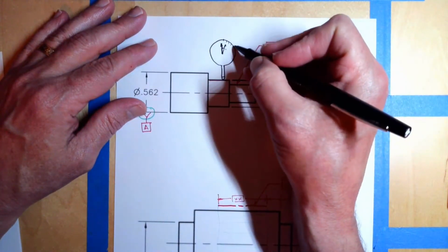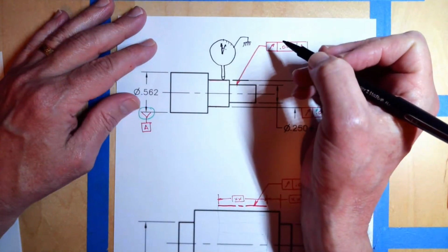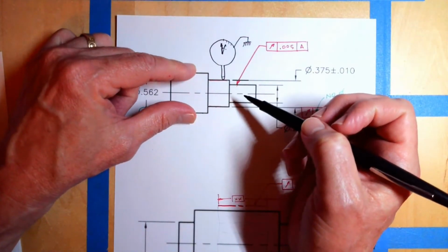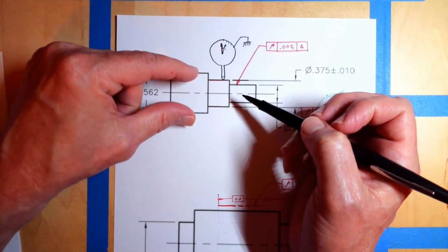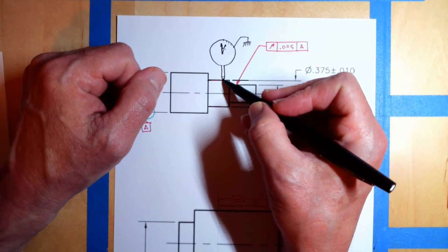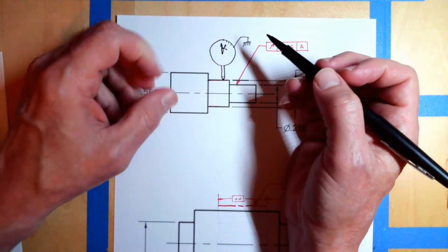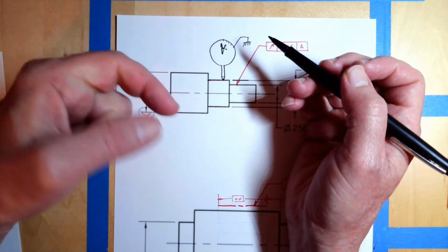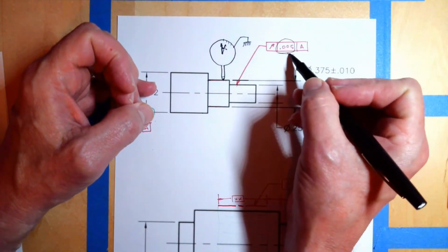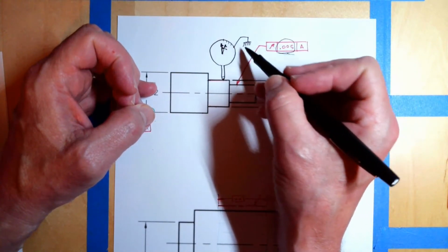And so what you do is you take the dial indicator and you mount it to something that's fixed, so it's not moving. And then you hold the part in the datum. So in this case, I would hold it in A, and I would rotate it. And as I'm rotating, if the surface is uneven, then the little plunger is going to go up and down, and I'm going to see this arrow move. And that's going to indicate that it's out of round, or that there's runout error. Basically this says that this is the amount of allowable runout error, in this case 5 thou. So I can have total needle movement of 5 thousandths and no more.